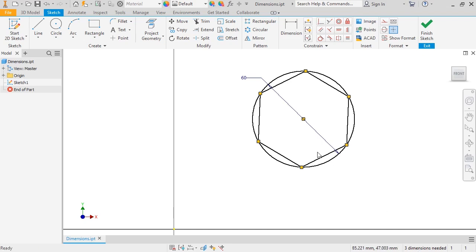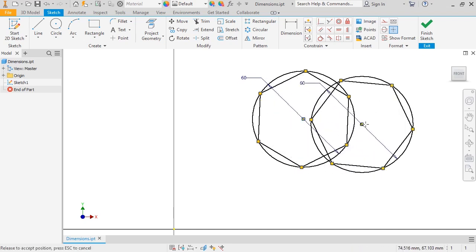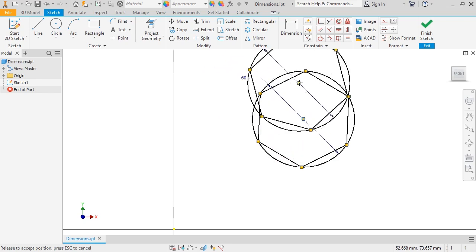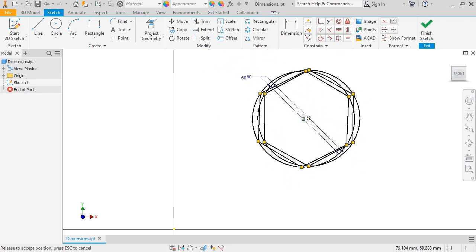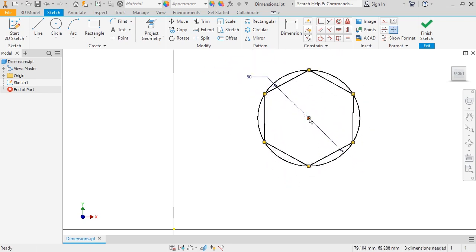Remember how a moment ago I was able to change the sketch's size and location by dragging around the sketch? If I try and drag the sketch now, notice that only the location changes. This is because the diameter dimension is now driving the geometry, meaning that it is a parameter for the model. This relationship between dimensions and geometry is the basis of parametric modeling, and means that if I want to change the sketch's size in any way, I'd need to edit this parameter.